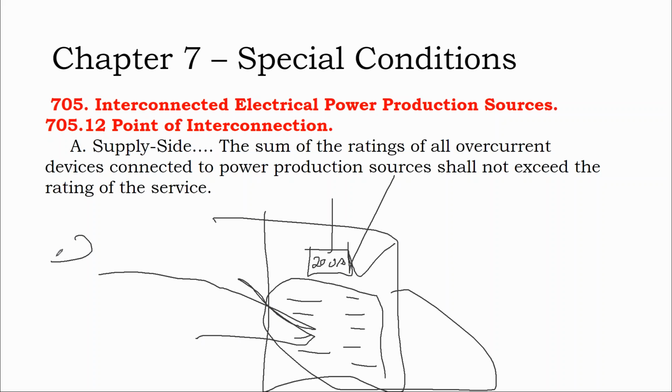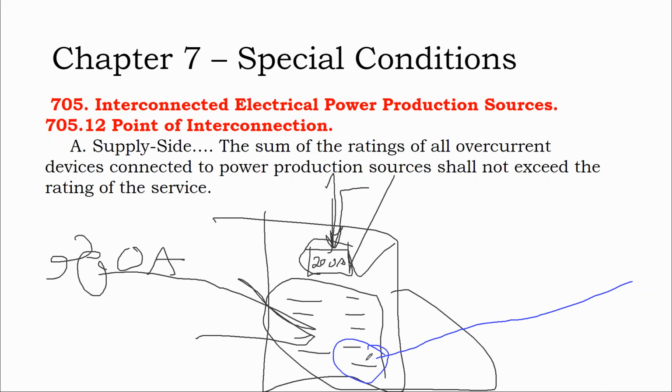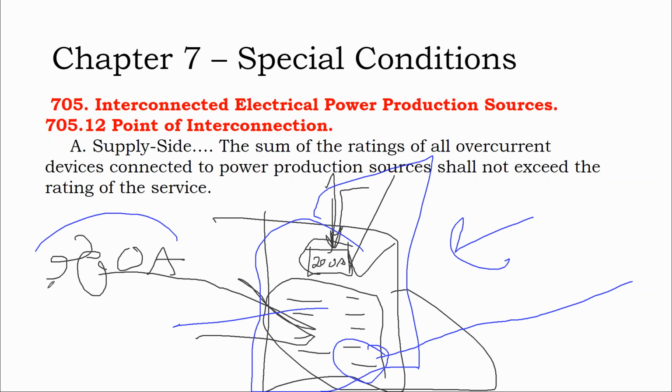And so if you have 300 amps of breakers and you put solar on the supply side, it doesn't matter because you can only pull in 200 amps because of the size of that main breaker. If, however, you put solar on the load side, you could pull more than 200 amps through this 200 amp service panel because the breakers are so many.